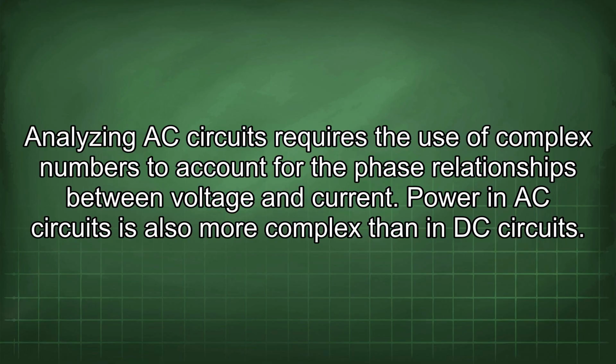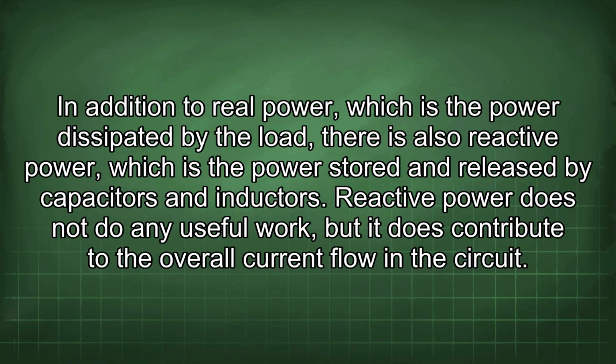Power in AC circuits is also more complex than in DC circuits. In addition to real power, which is the power dissipated by the load, there is also reactive power, which is the power stored and released by capacitors and inductors. Reactive power does not do any useful work, but it does contribute to the overall current flow in the circuit.